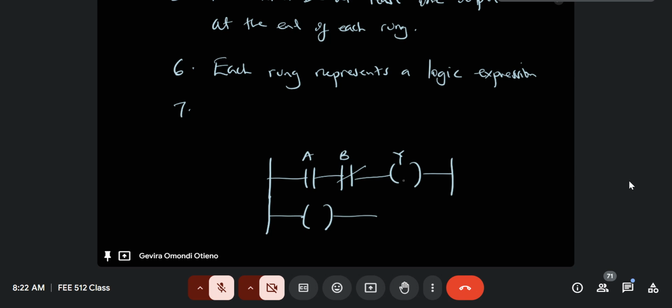So now remember, let's say there's a state here that I need. I need this state 1 to be used as part of the input, as part of the instruction, because maybe in the first rung, I needed to achieve that logic 1, but I need to use that logic 1 as part of the instructions for the next rung. So because the rule does not allow me to use a coil or an output as an input, I'll have to draw or replace that input. I'll have to replace that input with just the normally open contact.